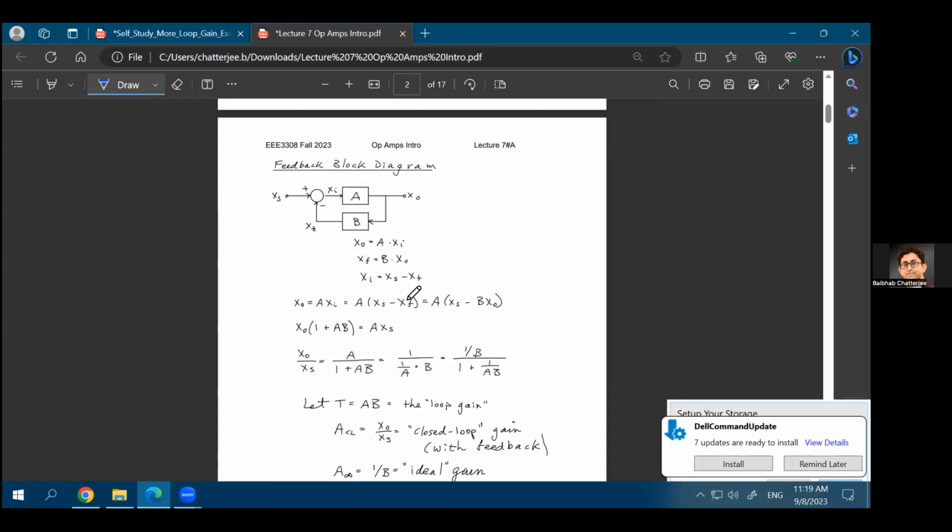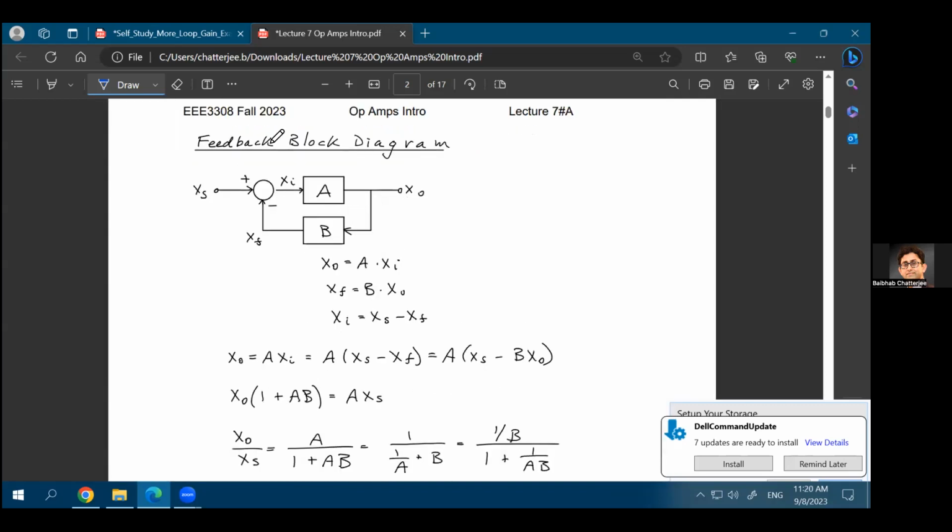More questions? Yeah. For that diagram right there, that basically points to the source being the positive of the op-amp. Yes. Feedback is negative. Yes. All right. So actually, what you were just asking, we are explaining in the next part with the feedback block diagram. You have your feed forward gain as A, your feedback gain is B or beta, and then you're putting it back at the negative terminal.